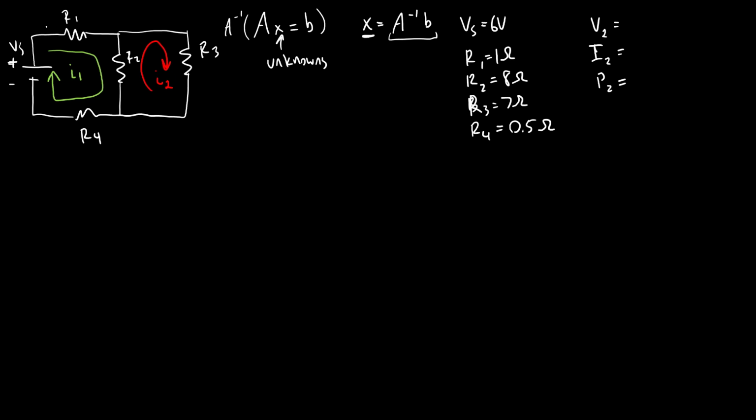Physical resistors are not polar. This is just a mathematical definition defining which way positive current flows. So you can go through and pick these whichever way makes sense to you, and then as long as you keep track of the signs, you should still get the same answers. So I'm going to choose, going from left to right here, plus and minus like this for all of my resistors, and we'll see where that comes in with our first step of this process, which is going to be applying Kirchhoff's voltage law to each one of these loops.